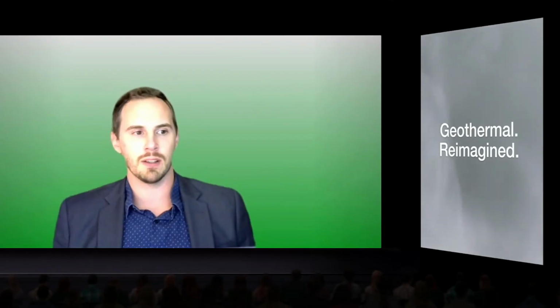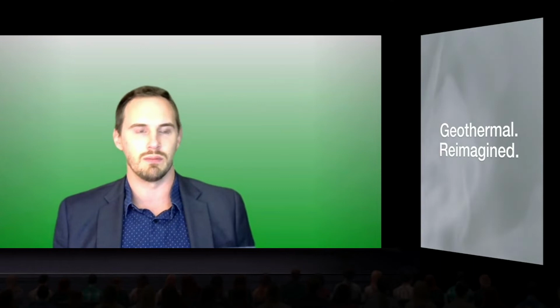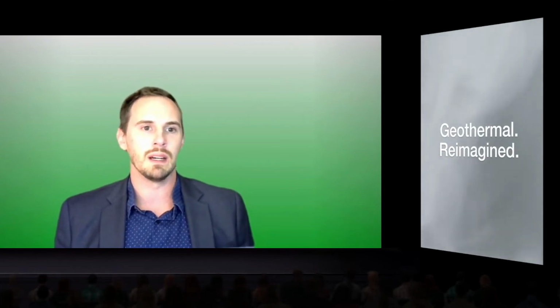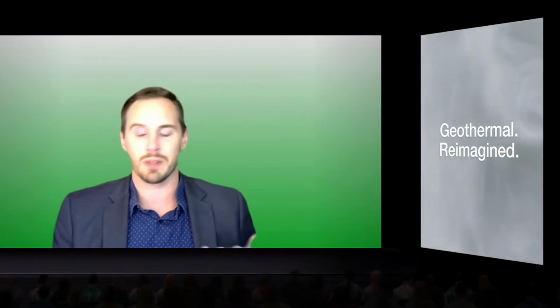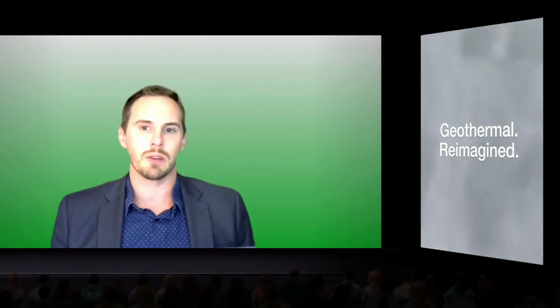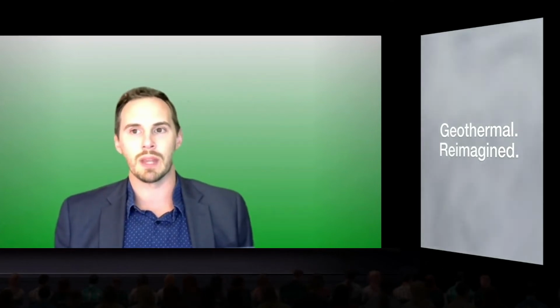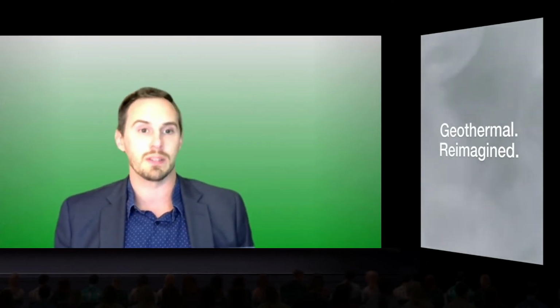Drilling, and specifically the role that oil and gas might play in supporting the advancement of geothermal drilling. Yeah, so totally agree with what Patrick said. It's not necessarily the technology that's out there that's going to be significantly increasing the ROP for these geothermal wells. I mean, of course, that does help, but it's really about how to reduce that flat time. And what that boils down to is how to increase tool life.